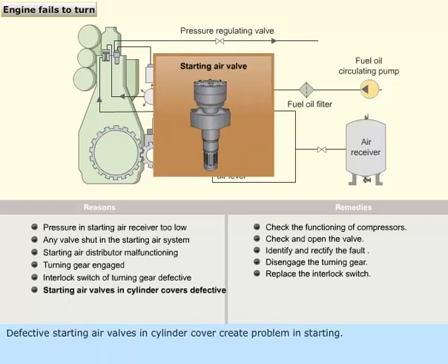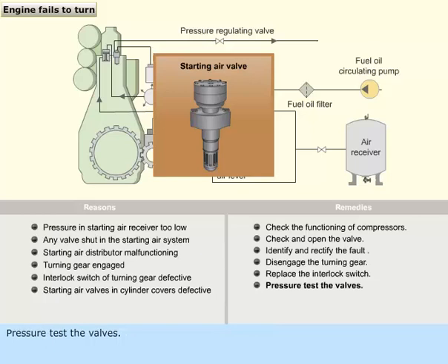Defective starting air valves in cylinder cover create problem in starting. Pressure test the valves. Replace or overhaul the defective valves.